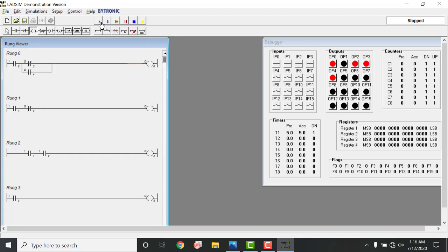Okay, let's start the complete simulation again. First close this. Okay, complete simulation. Now we are done with our simulation. Let's start it. Starting the complete process. Conveyor belt is on. The infrared sensor is detecting plastic material and the solenoid valve is active. When both of the materials are detected, the solenoid valve is stopped. When the infrared sensor detects the maximum limit of plastic material collected, it would send the information in 5 seconds. We start the timer, and after 5 seconds, yes, it is on.